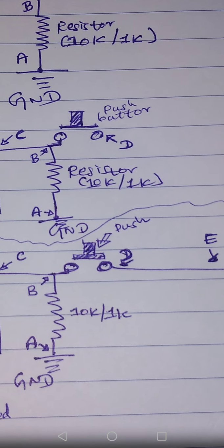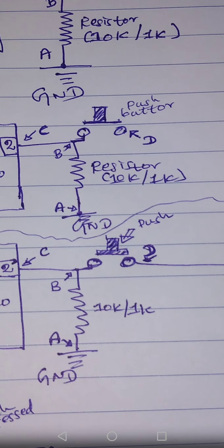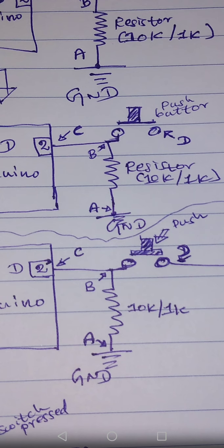So if you connect a digital sensor to this junction B instead of a switch, that can give plus 5 and ground according to the environment, and still there is no problem. If plus 5 is coming, plus 5 will directly go to pin number 2 through B and C. A will be ground, the resistor will handle the voltage. If ground is given by that particular sensor, then still no worries, because already we are giving ground. Both will be the same ground, because we will use a common cathode anyway.